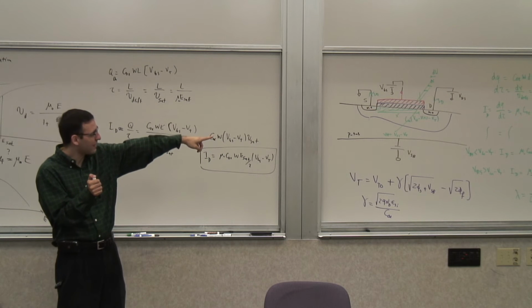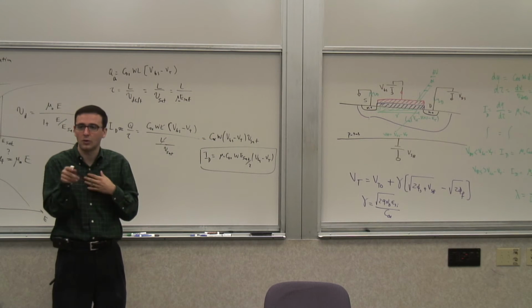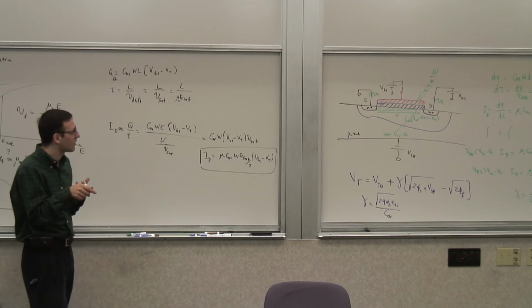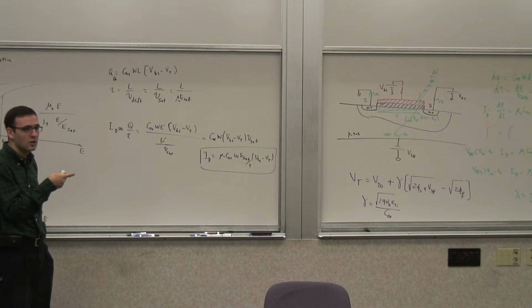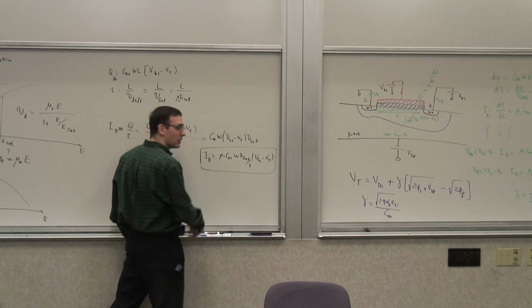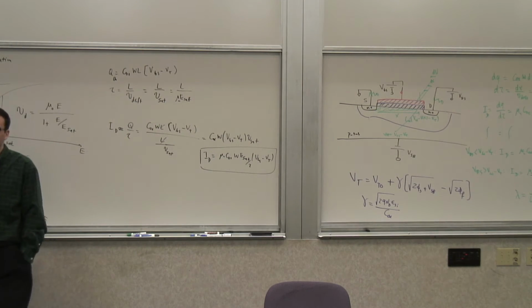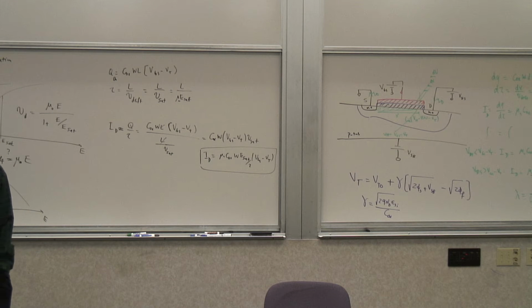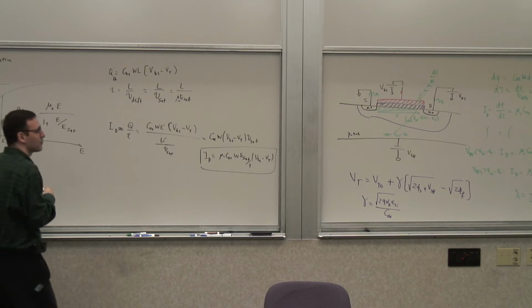Because that depended on L too, right? I_D had a W over L in its expression. But now I have lost the second effect. Basically, I can't get more current. But the speed by which I can charge and discharge a capacitor depends both on the current and the capacitor. I have reduced the size of my capacitor. And we'll see this quantitatively in a few minutes. So it does still help, it turns out.